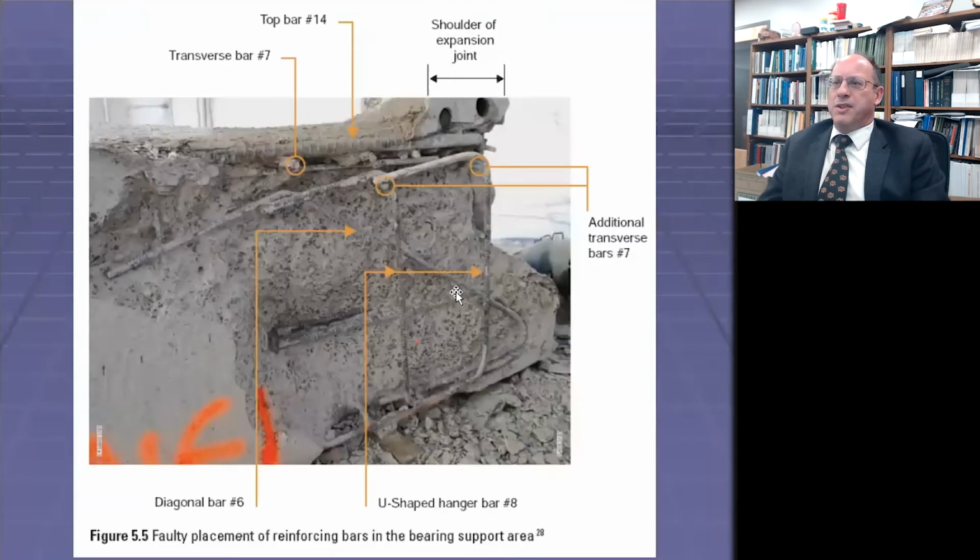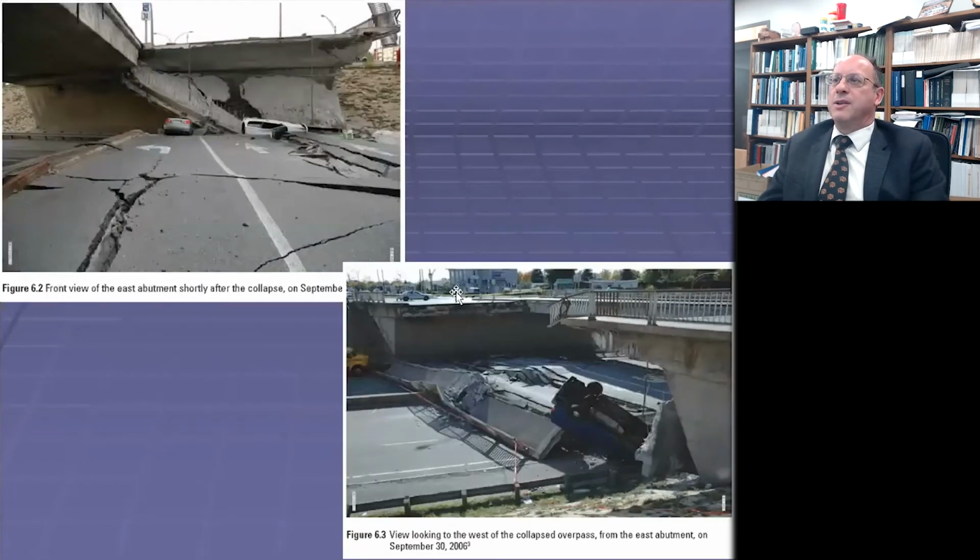And then in the post-mortem looking in, you can kind of see that we have some problems of concrete quality, but you also see that you've got a fairly extreme top bar effect with those number 14s, where essentially the bottom of the bar doesn't even look like it's buried in the concrete.